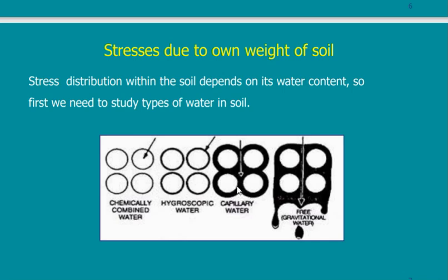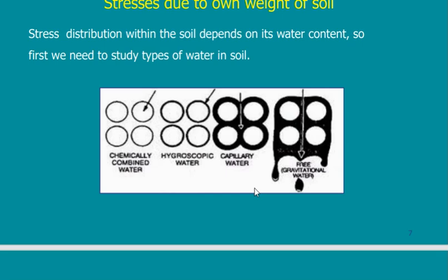I have capillary water. You heard about capillary water. Capillary water is the water that can rise inside the voids of the soil till it reaches a certain level, and it does not go beyond it because of surface tension, because of the suction forces that are developed inside the particles itself. The tension between the soil, the water, and the soil particles.